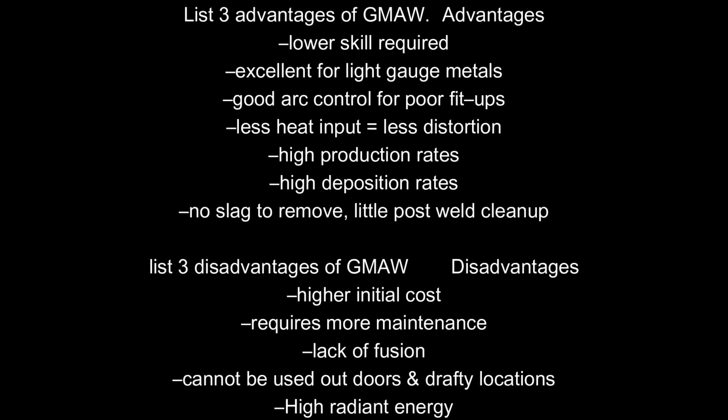List 3 advantages of GMAW. Advantages: lower skill required, excellent for light gauge metals, good arc control for poor fit-ups, less heat input equals less distortion, high production rates, high deposition rates, no slag to remove, little post-weld cleanup.